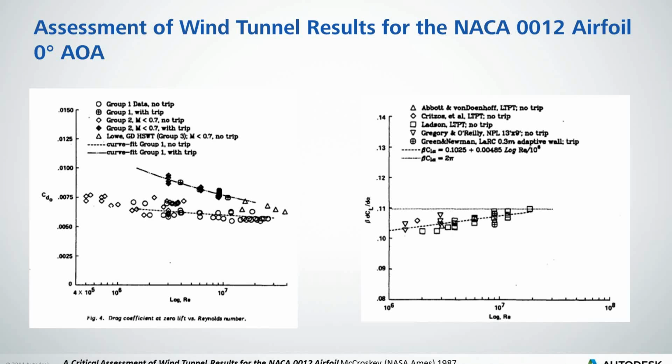Within this plot, how does CFD really match into these trends? Simulation CFD at Autodesk, at least at 0 angle of attack, is right about there. So to me, it's quite within reason with all the other wind tunnel experiments in terms of 0 angle of attack.